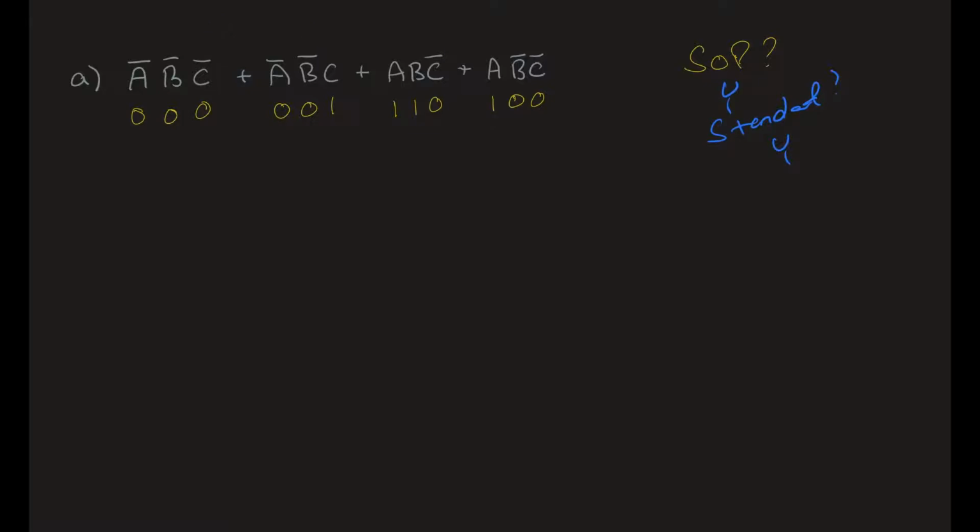Alright, so what size K-map do we need here? Well, we've got 3 variables, which tells me we need 8 cells. So remember, that's the vertical rectangle thingy. That's a technical term. Cut it in half. Boom.